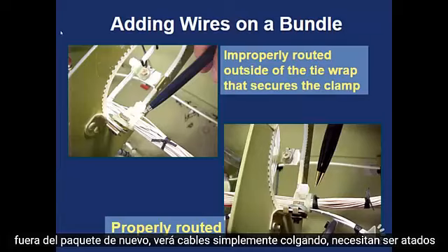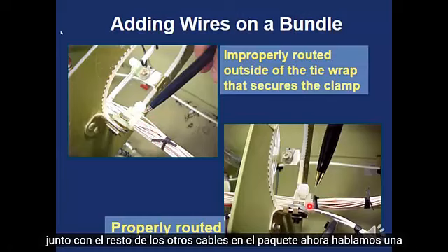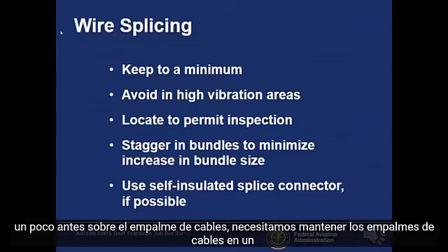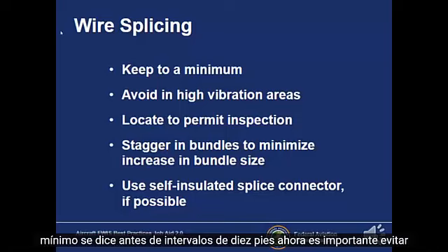Again, you see wires just hanging out. They need to be bound together with the rest of the other wires in the bundle. Now, we talked a little bit before about wire splicing. We need to keep the wire splices to a minimum. It's said before, 10-foot intervals.